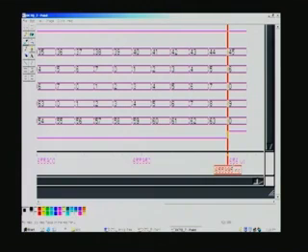Each block is 64 bytes, therefore it is 65536, which you know as 64K. So you see the entire image has been processed at exactly 1 pixel per 1 clock cycle. This proves the first statement we made at the time of explaining the algorithm.